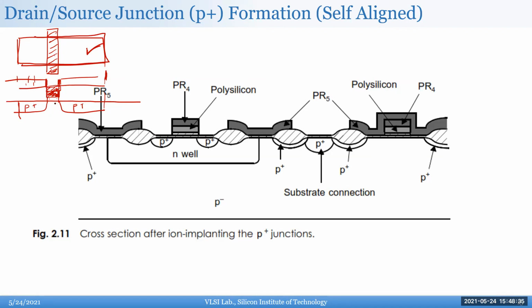And the resistors in an IC design process, and again tomorrow we'll talk more about resistors, are actually done through the same polysilicon as the gate. Now what they do in resistors is, because you want that to be highly resistive, you actually don't do the saliciding. So they stop the saliciding to give you a high value of resistance. So that's how you fabricate resistors in most IC design processes.